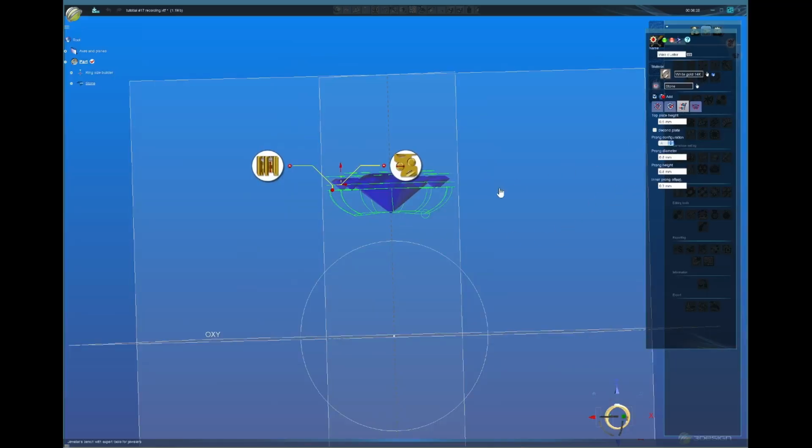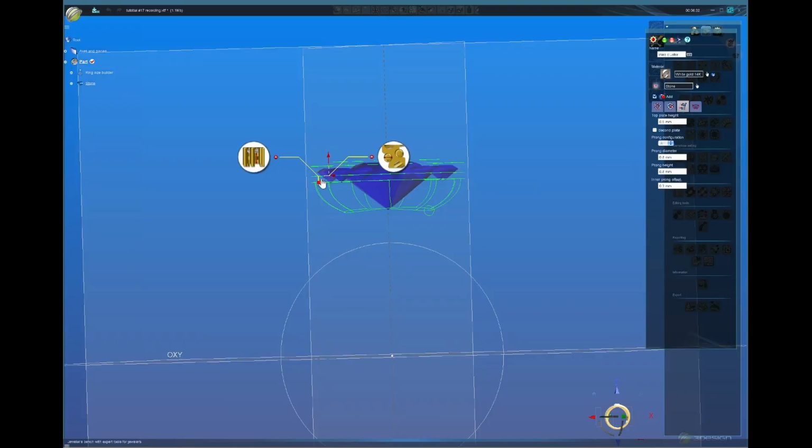First, top plate height. Top plate height is this part here, okay? You can do with only one plate or you can do two plates. In our case, see that as soon as I clicked on the second plate, it gave me this part here. But for this demonstration, you're gonna do just one plate. Click on it. And I want my plate to be 1 millimeter.